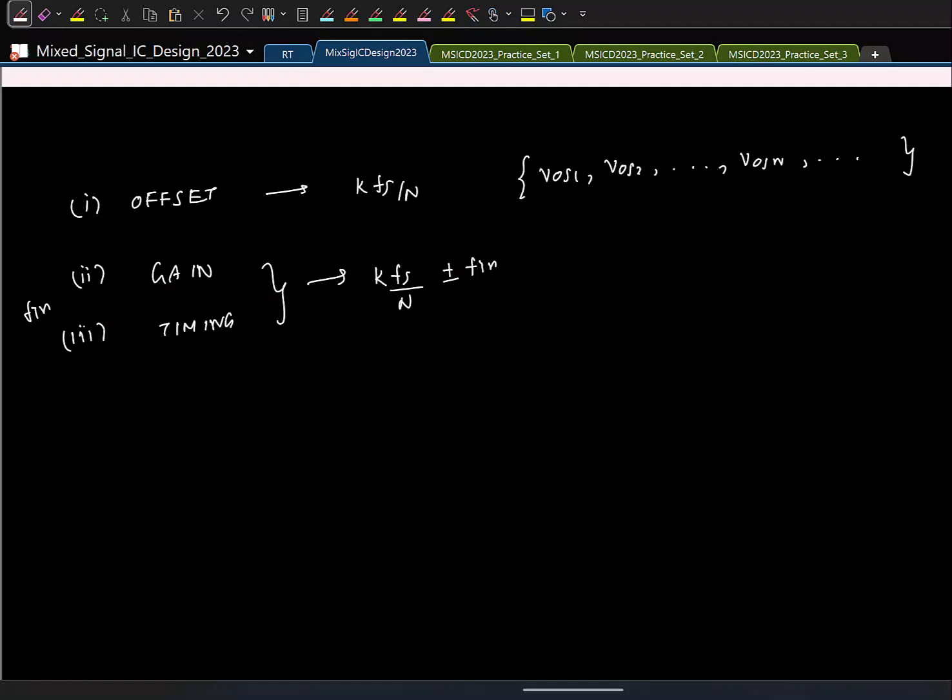And as I mentioned, this time interleaving is the way in which all high-speed ADCs are designed, especially in serial links. And it is not uncommon to have the number of channels be 64 or so. And in all these serial links with wired communication, these ADCs are really required, because in this wire transfer through USB or LAN, you are interested in transferring ones or zeros. So ideally you want to transmit for 0 something like this, 1 something like this, let's say 0 1 0.